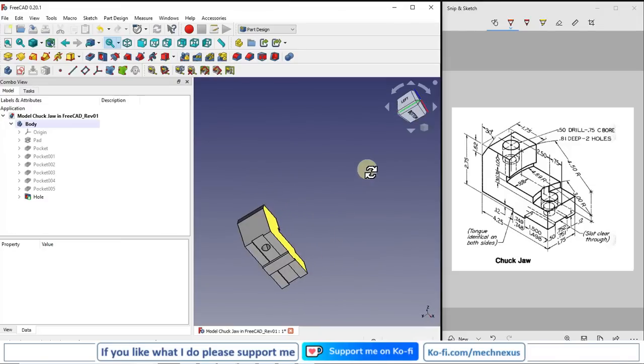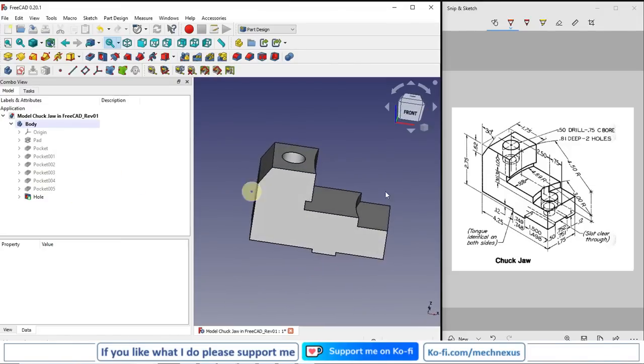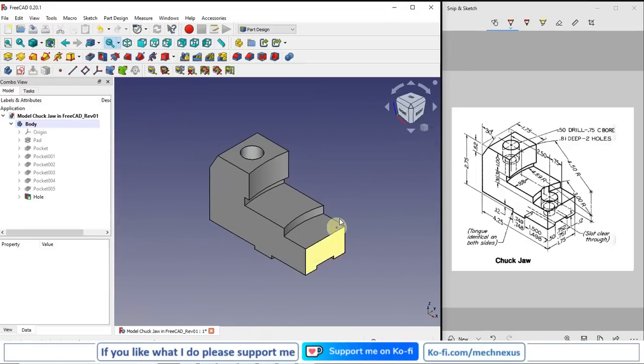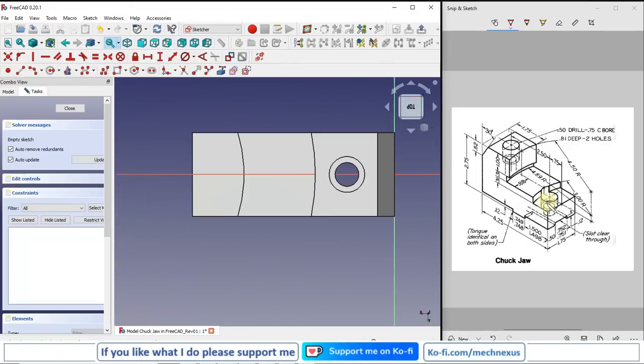So you can see that we have successfully made this hole, and we will make same hole features at this surface here. So I will go for the isometric, and I will select this face and I will say sketch, and position of this hole is 0.75 from the edge.